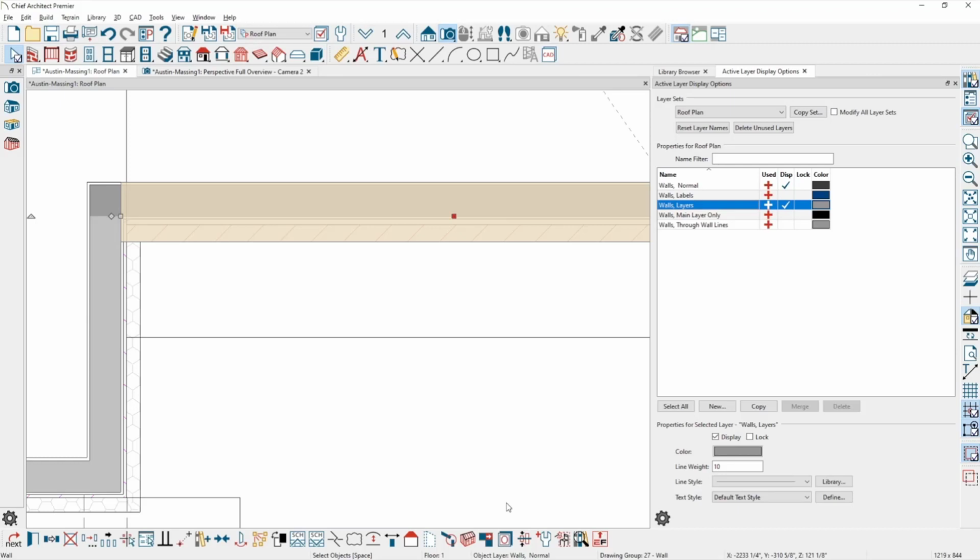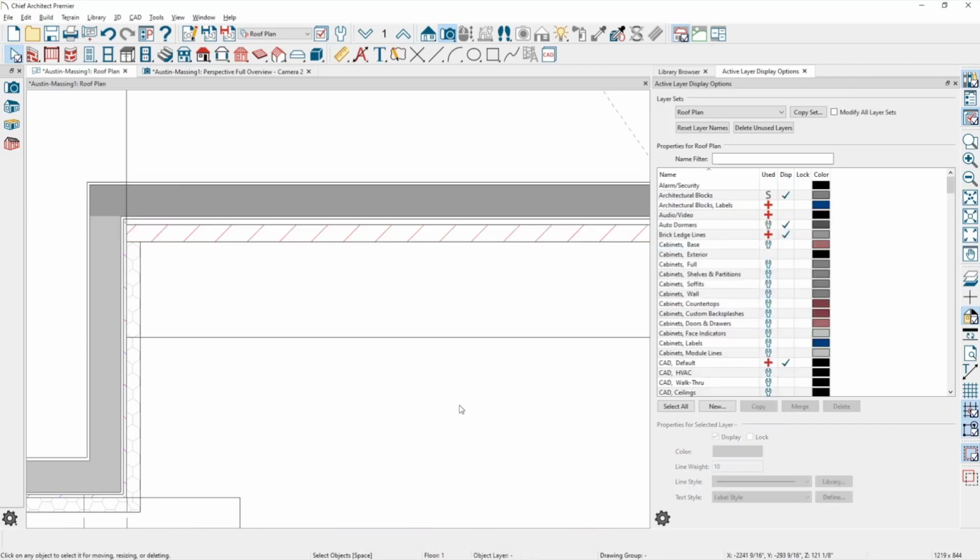Well, one way to do it might be to customize that wall type and turn off the fill for your stud. If you want to see it in your floor plan view, then it would look different. Let me just see if Al may still be out there and has any idea what we might do to that wall to get what you're after.